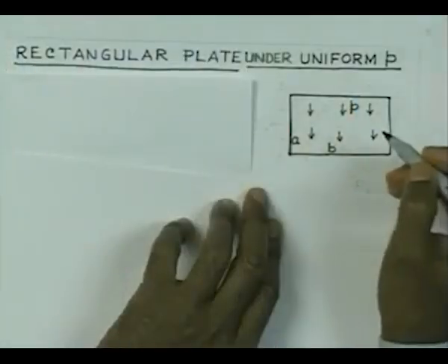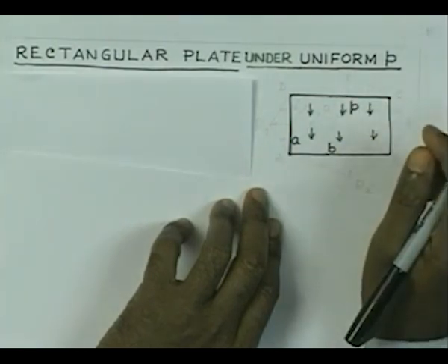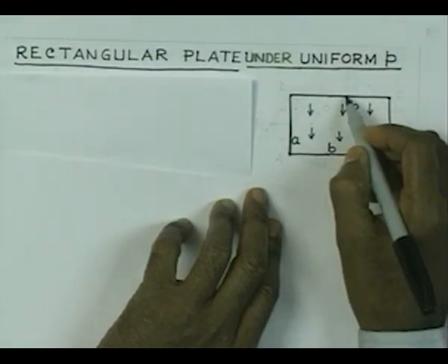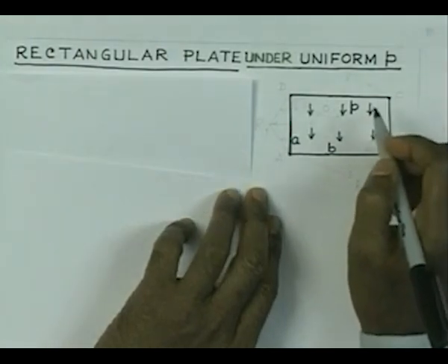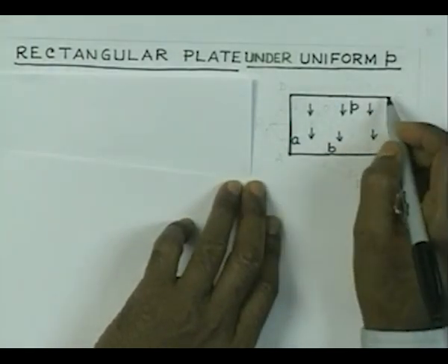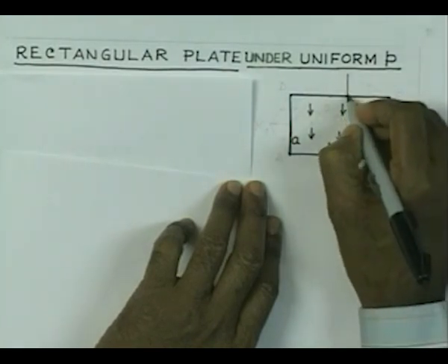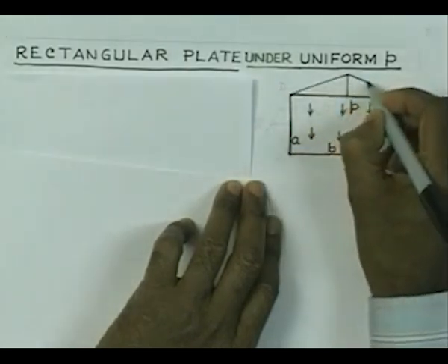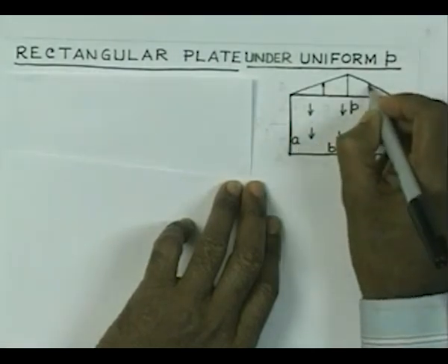Here the center of loading is exactly at the center of the plate, and these middle points of the sides are closest to the center of gravity, and therefore, what you find is that reaction is going to be non-uniform and it is going to vary along the boundary. If we just assume that the reaction forces at the boundary are going to vary linearly, then we can consider that the reaction is going to be the maximum at the center of the side. So, therefore, the reaction forces are going to have a distribution like this over this boundary.